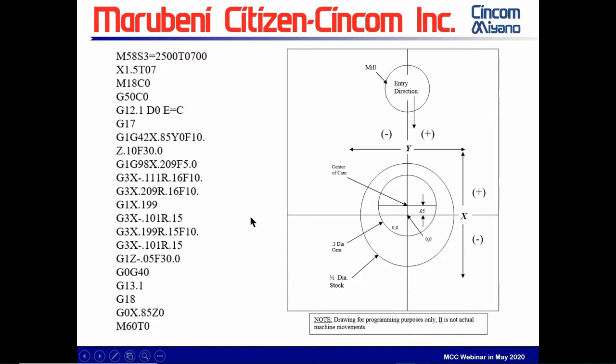Hey, Ron, I got a question here. Since you were using cutter comp, what P-value should I put in my T-data page? The P-value is an 8, because that is the center of the cutter. The P-values on cutter comp, basically 4 is for front turning.